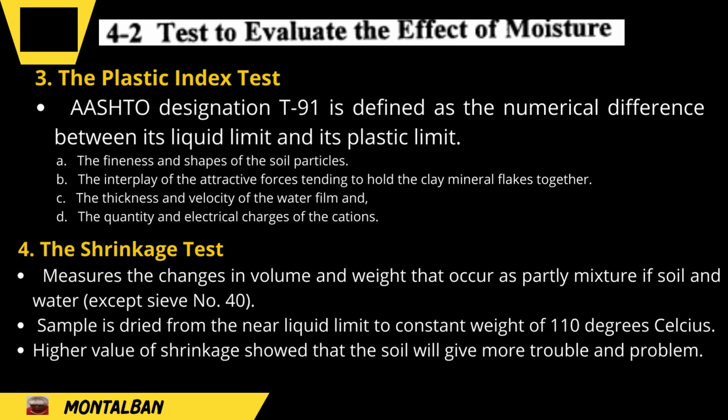The volume of a certain soil increases when it absorbs water. Soils that are suitable for subgrade and base course are those that expand very little when moistened, and those that swell more are considered poor materials. A common soil specimen requires a volume change limit of 1% for base course materials.